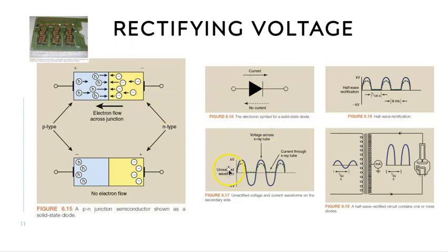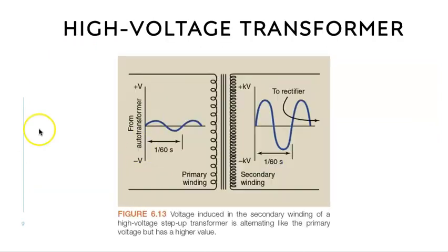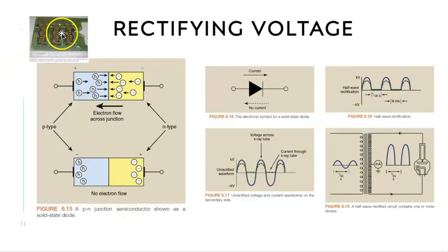What this is saying is that we have our energy here. We still have alternating current. Now it's going to pass through these circuit elements that say, okay, we'll conduct electricity for you in this part of the waveform, but not here. It's going to stop the electron flow there. It's going to let electricity flow, but not down here. So what we end up getting is something that looks like this. Flow of electrons, nothing. Flow of electrons, nothing.